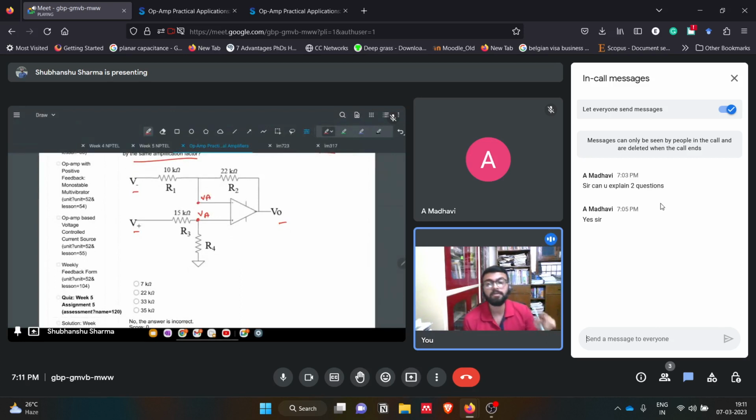First of all, identify whether it is a negative feedback circuit or a positive feedback circuit, like whether it is behaving like a non-linear circuit, or as a proper ideal linear circuit. Here, since it is negative feedback, we know that it will be working in linear mode. It will be showing linear characteristics, so that's why it can have virtual short characteristics.